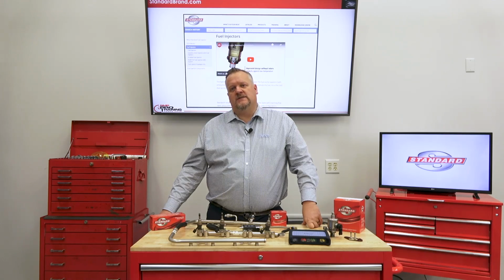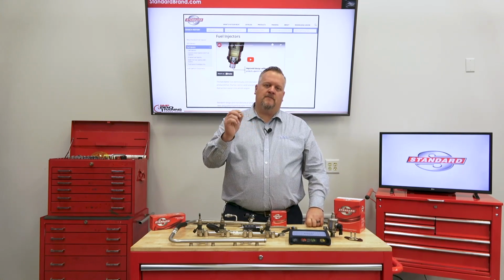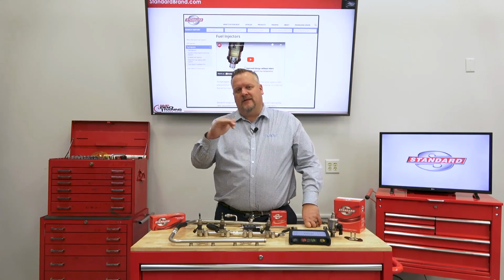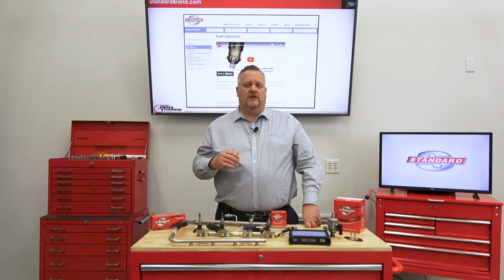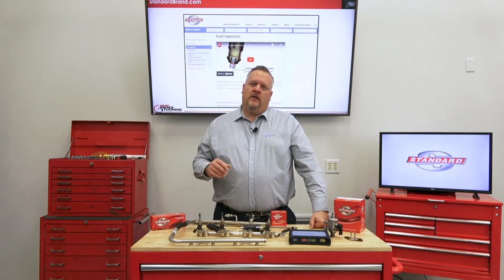The first one that caught my attention was, will ignition problems affect fuel trims differently than fuel injector problems? That's a good question. Ignition problems will show up immediately, like if an ignition coil's shorting out or misfiring. We might see a little blip in the fuel trim, but it'll come back to the normal value. Now, a fuel-related or airflow-related issue is going to have a significant impact on the fuel trim reading.